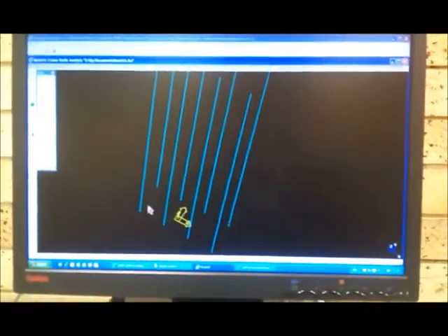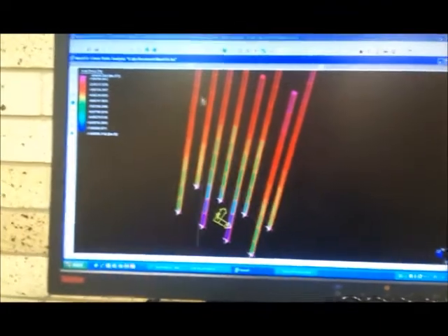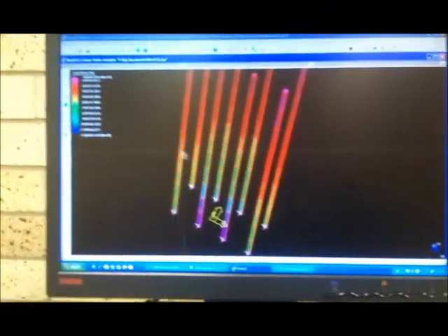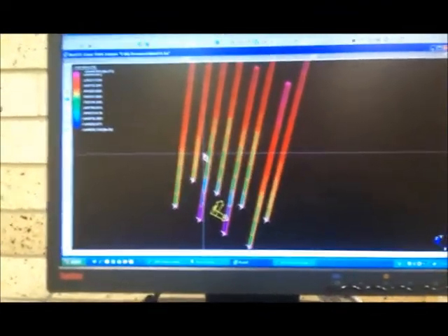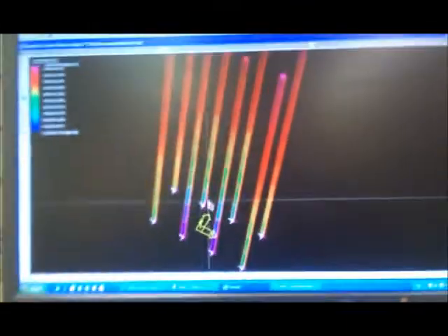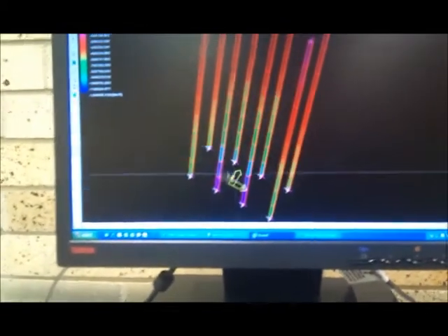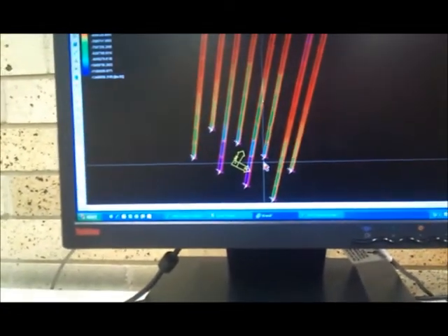Now, as you move up along these columns, you will find that the stress is very low. So actually what one can do is one can reduce the size of these columns. Yes, because we don't need all of this material, isn't it? Okay, now we have checked these columns. Lots of them are over designed, but none of them is unsafe.